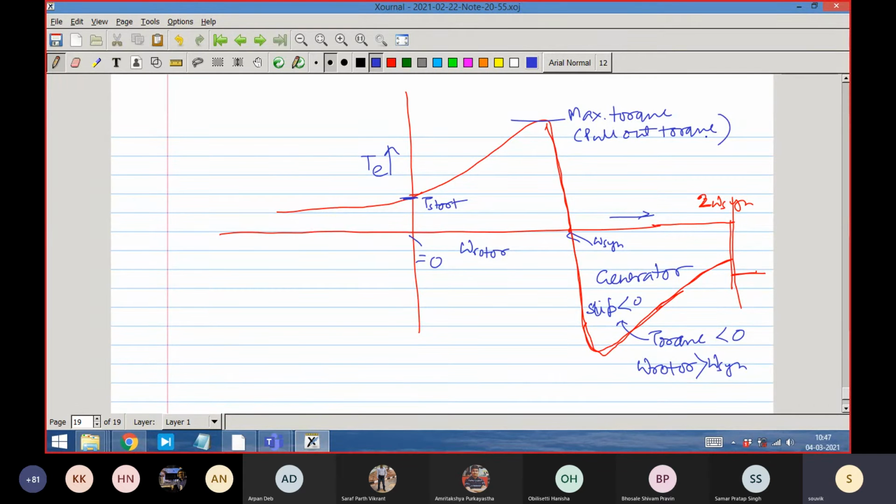So okay. This is the intrinsic characteristic of torque generation of the machine. Intrinsically, it is generating. The rotor speed you are increasing. You have given a stator supply. Based on the stator supply, the synchronous speed is developed. The magnetic field is rotating at a certain speed, and rotor speed can vary. So depending upon the variation, we are putting this variation with the characteristics of slip. So this is called slip is equal to 1, and this is called slip is equal to 0. This zone is slip is equal to -1.